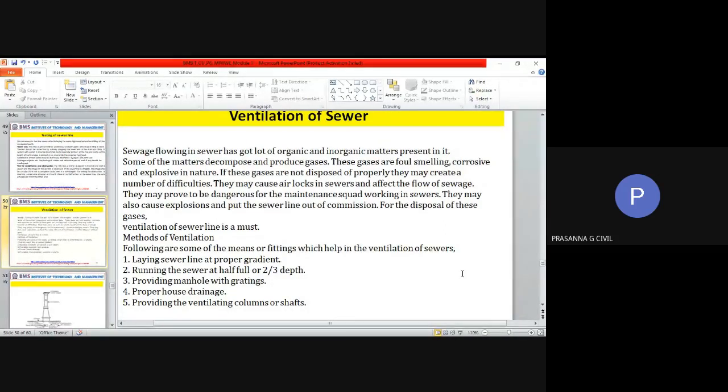If by mistake they have used a lantern or something, putting it down, sudden flare up will happen because these gases have built up and these gases have calorific value. So if subjected to small heat, temperature, etc., and they get ignited, they will burn. So many such accidents do happen, and because of that, you need ventilation in your sewer system.